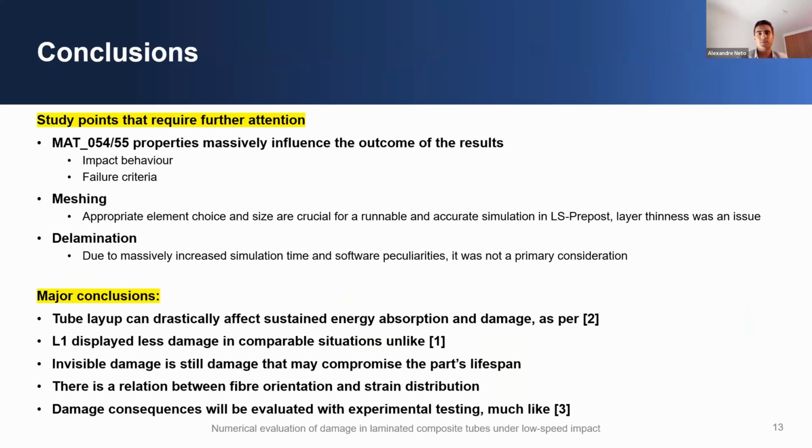Starting with the study points that require further attention, I found that MAT55 properties massively influence the outcome of the results, not only affecting impact behavior, but failure criteria limits as well. So it is critical to insert the correct values in the MAT card.